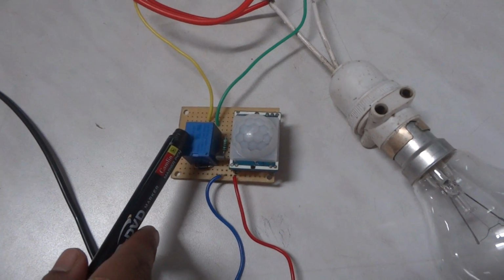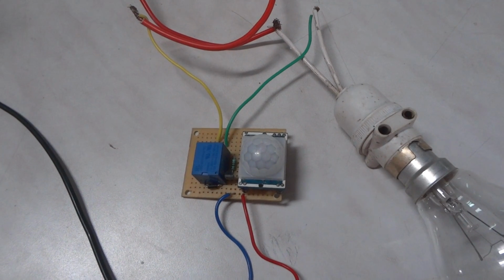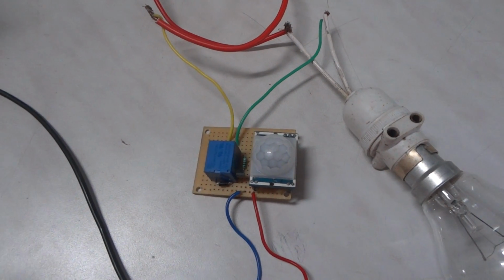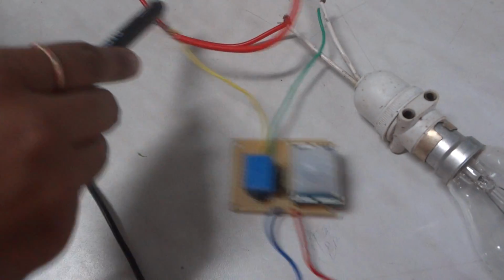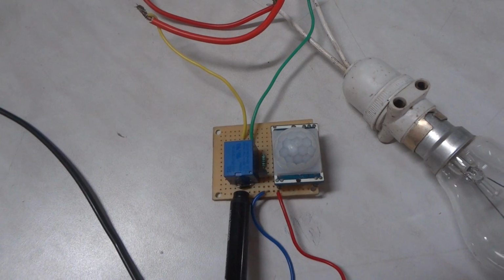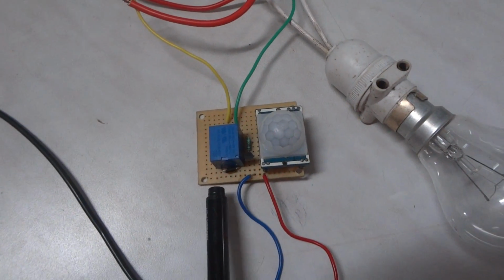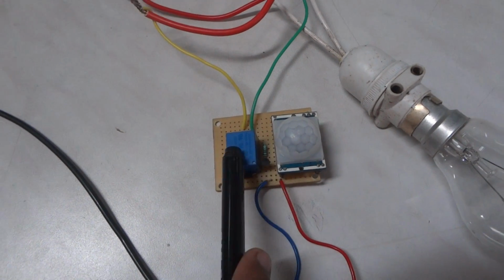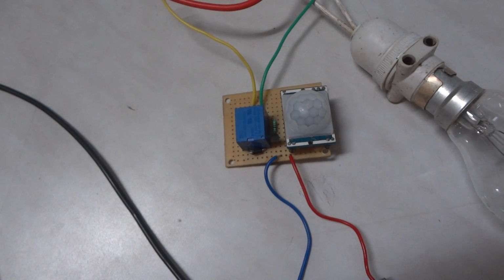Relay is an electromagnetic switch which is controlled by a small current, and it is used to switch on and off a relatively much larger current. It is used to isolate the AC circuit from the DC circuit. A freewheeling diode is used to eliminate flyback, which is the sudden voltage spike seen across an inductive load when its supply voltage is suddenly reduced or removed.